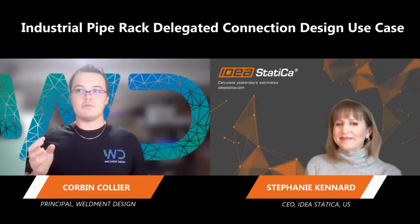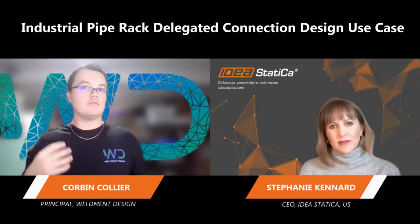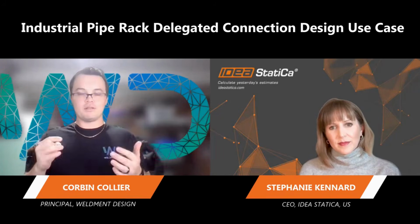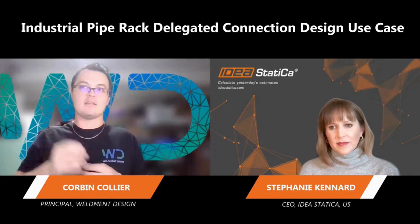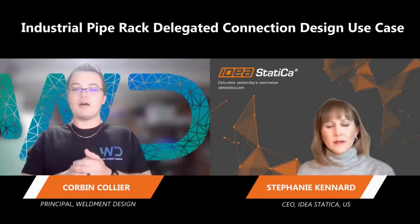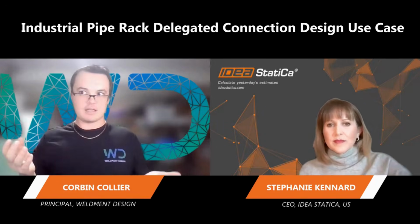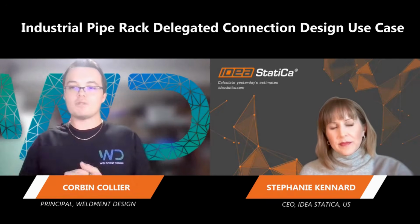And what's really nice about those viewers is that persons can then pull out the IFC models, they can pull out DWGs, really. Between the two of those, typically persons can then pull all the information they need. They can even dig in and find the weld sizing, so we can make sure that we are talking apples to apples. They can take that IFC model, drop it directly into their model, whether that be SDS or et cetera, and see the overlay, see if everything's matching up.